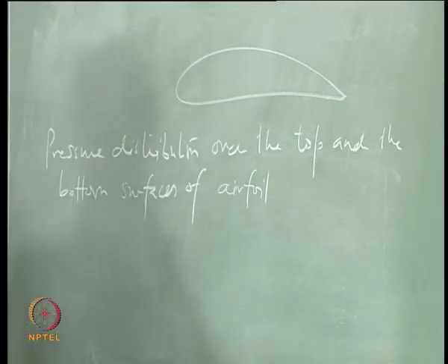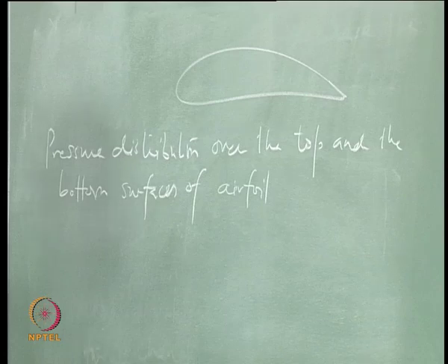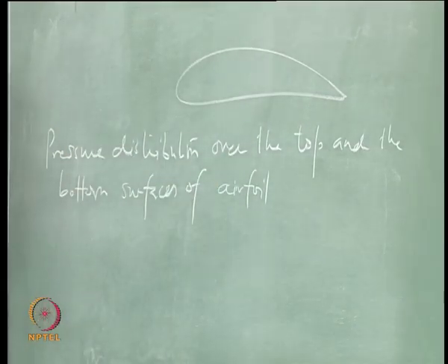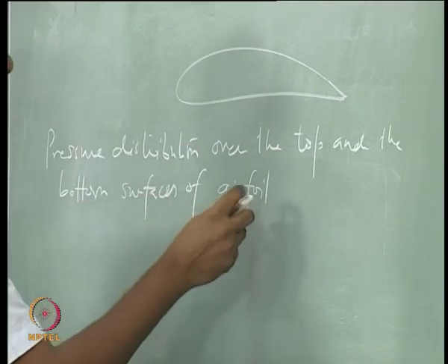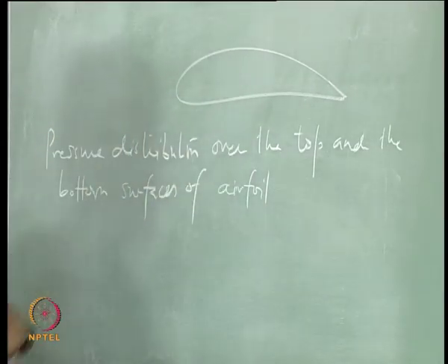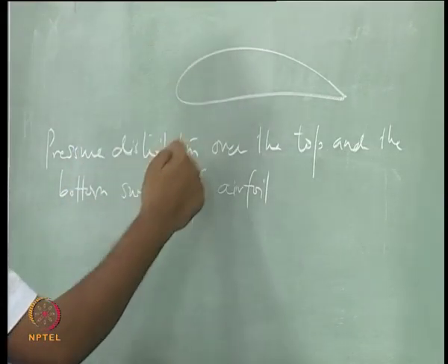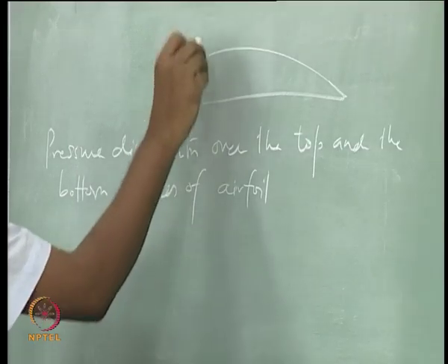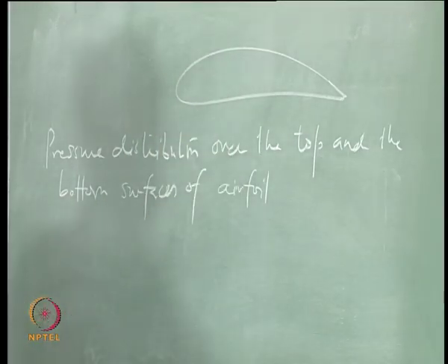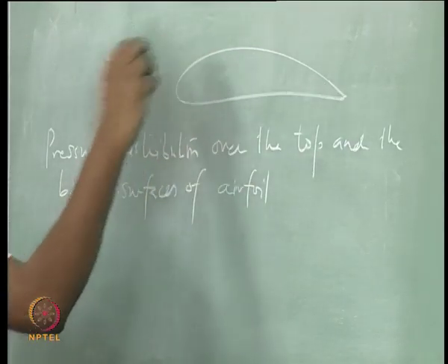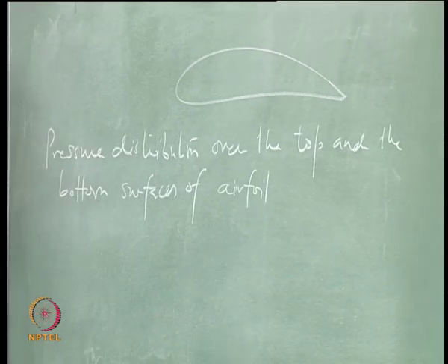The resulting load due to the pressure is what is giving us the lift. And if the loads coming from the pressure on the top surface and the bottom surface are not lying on the same point, then they are going to give rise to a moment, right.